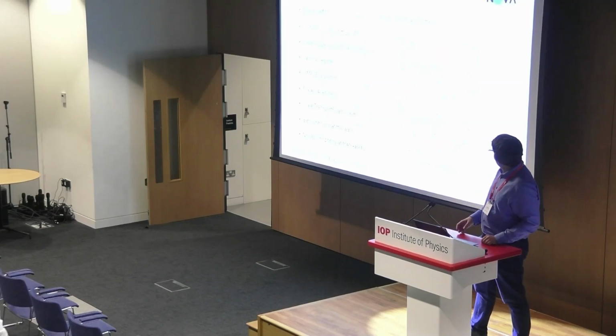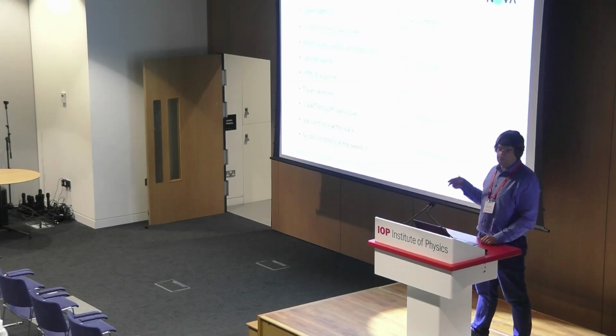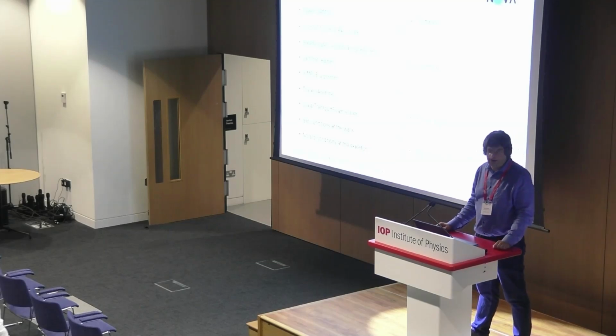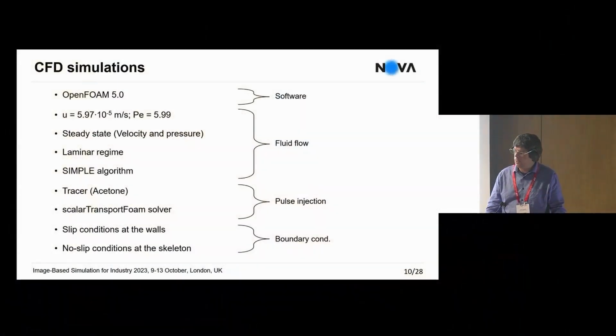So as I was saying, we performed CFD simulations. It was done already some years ago, so it was still version 5.0. But basically we solved the Navier-Stokes equations, so we obtained the velocity and pressure fields, and then we simulated the tracer injection through the column in order to obtain the residence time distribution curve.